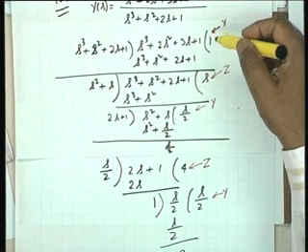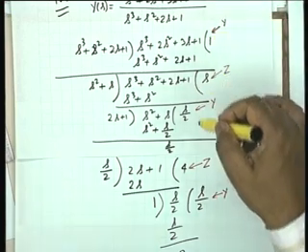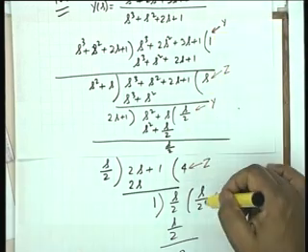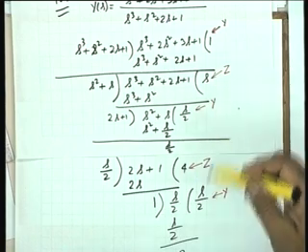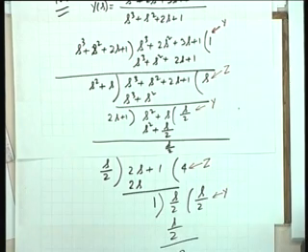Because the continued fraction expansion yields terms like 1, s, s by 2, 4, s by 2, which are resistors, inductors or capacitors. Right? Therefore it is PR. Therefore it is realizable. In fact, the network is obvious. I will draw the network in a moment. Network is obvious, but I want you to make another conclusion about the result that we have got. That it is an RLC network. As simple as that. It contains resistors, inductors as well as capacitors.